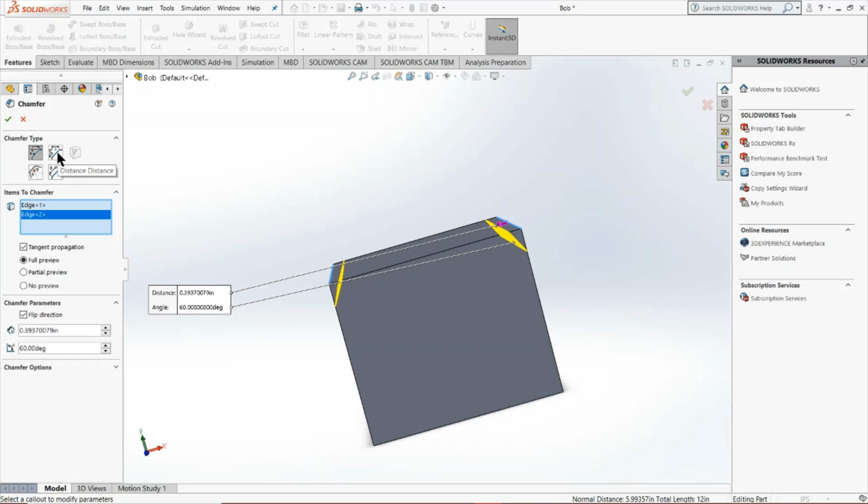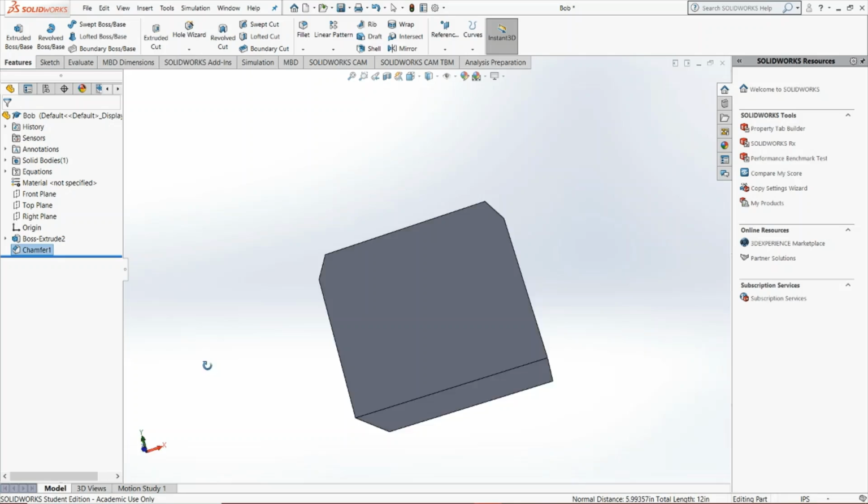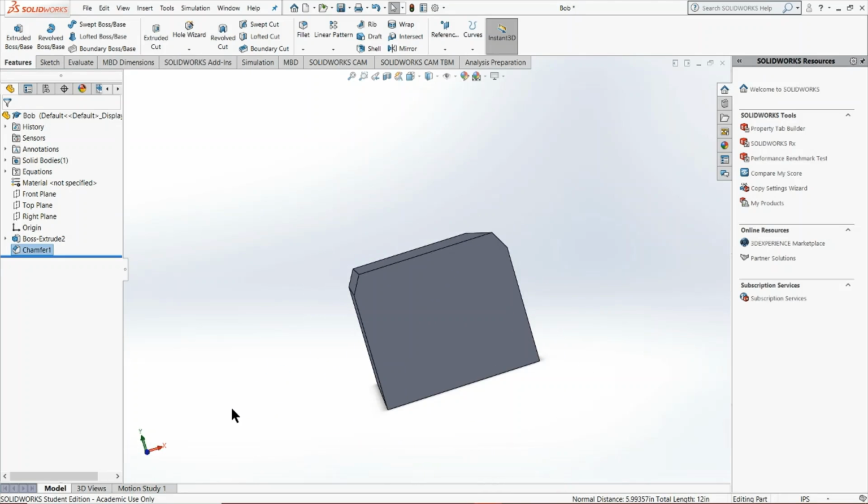Furthermore, you could also change the type of chamfer. So say the angle's not doing it for you, you could change both the distances. You could change pretty much the hypotenuse of the chamfer. It's entirely up to you. So I press OK there, and you'll notice it's slightly more boxy. It's not shaped like a piece of toast.